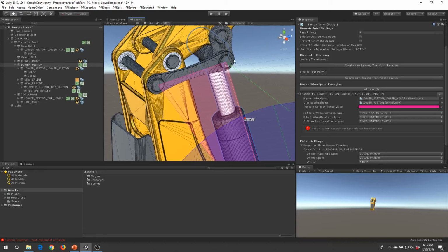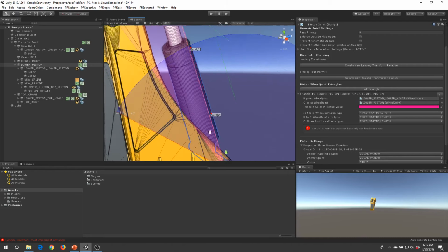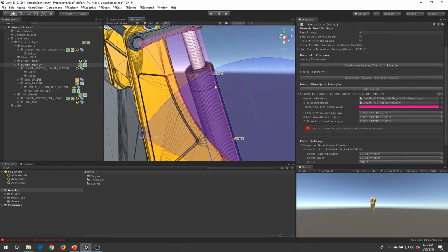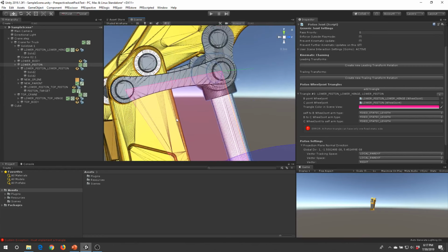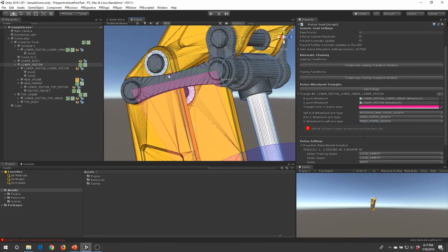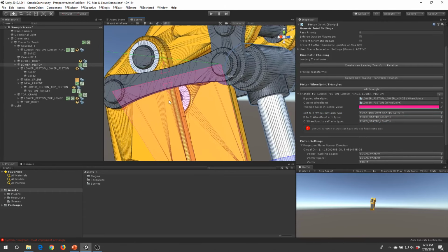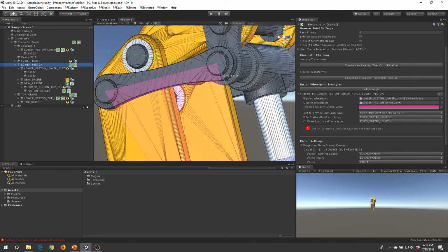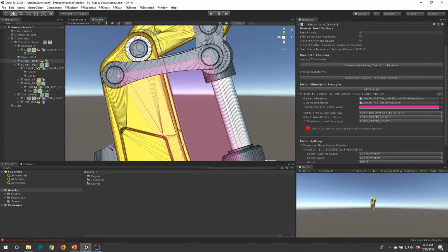So point A is over here, point B is over there, and point C finally is over here. So first thing we want to do is set the first to A to B direction, which is the first one, self to wheel joint arm type. And it's actually rotary, but it's static in length. We can change the length of this particular hinge segment. So what we need to set is rotating arm, but static length. And that's also going to change the icons, and I hope you can see it over here, to a double triangle, which is indicative that it's actually movable.